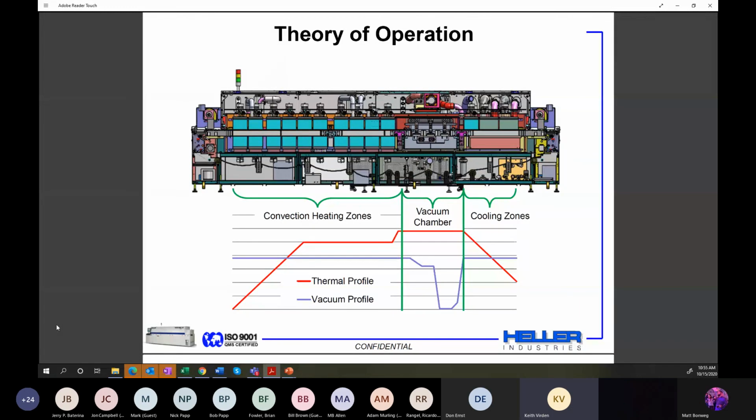What we found is that's most important is that during vacuum you stair step it. So you bring it down, slowly pull out some of the larger voids. And then when you take it to whatever this is, the 5 to 20 torr, that's where you release the rest of the voids. And if you do that slowly, it'll reduce any solder splashing.